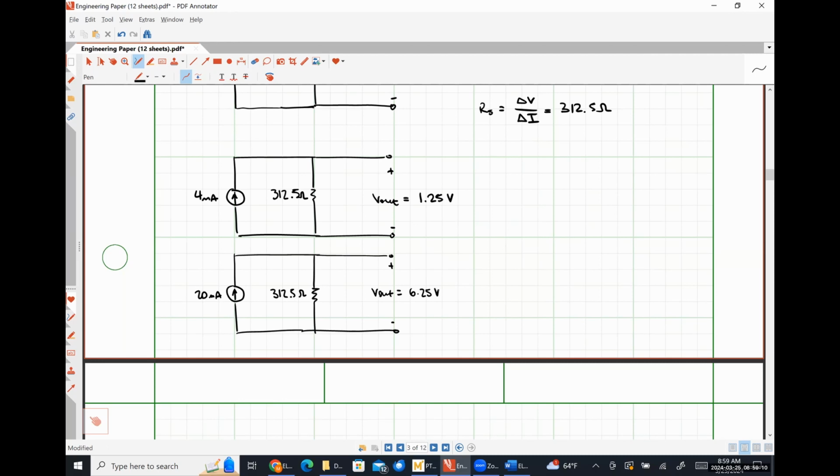That's where the op amp circuitry is going to come in. The practical current source is effectively going to be connected to either the inverting input or the non-inverting input, depending on how you choose to approach the problem. Then the op amp is going to be used to effectively get rid of that 1.25 volts of offset. How might we subtract something? A difference amplifier, right? So, giving you extraordinarily strong hints about design project 1, problem 2. Let's look at problem 3.